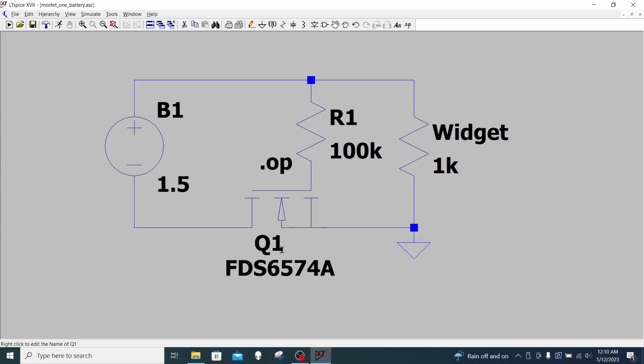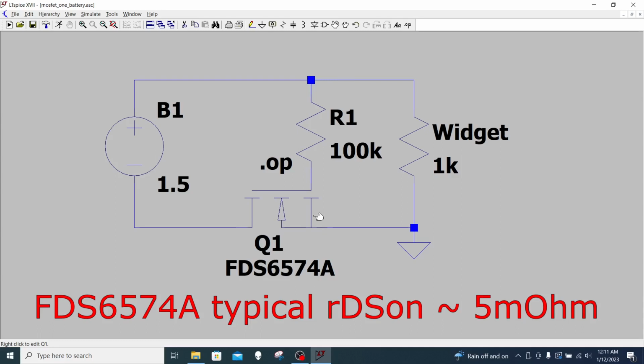Depending on the MOSFET, it might be anywhere from some milliohms to several ohms. Generally speaking, when you bias that transistor on, that resistor, that RDS on, is generally going to drop a lot less voltage at a modest current than the body diode would.